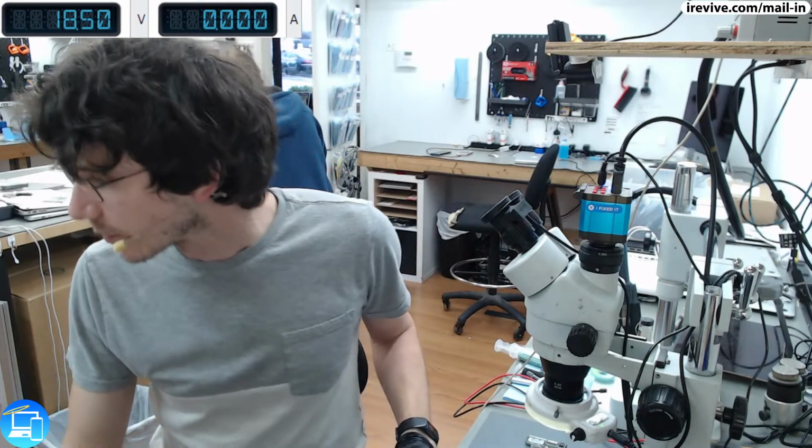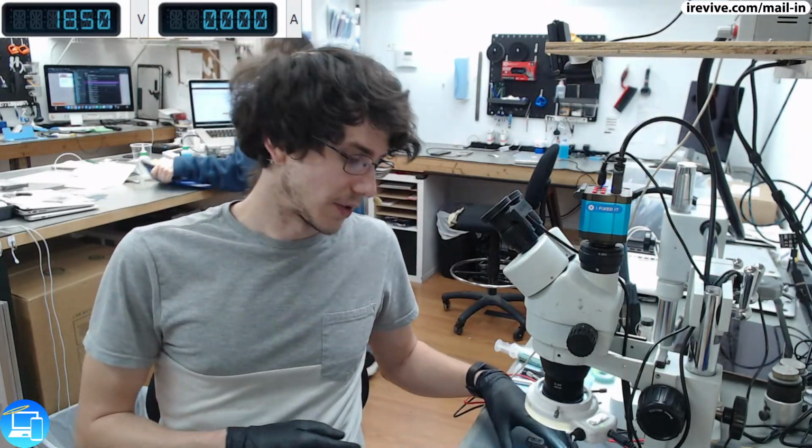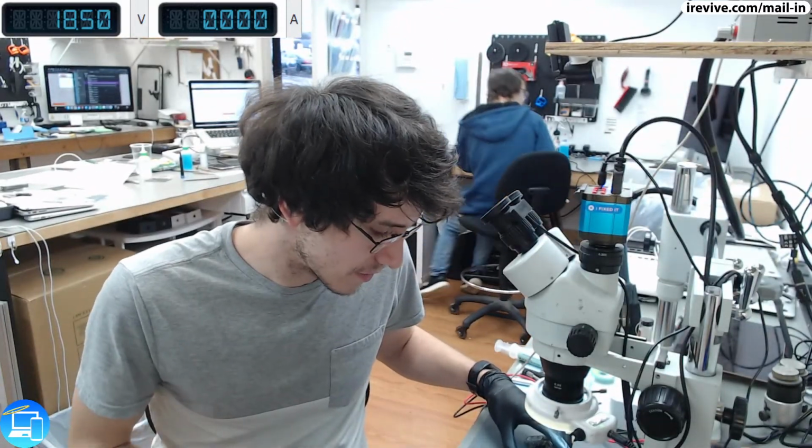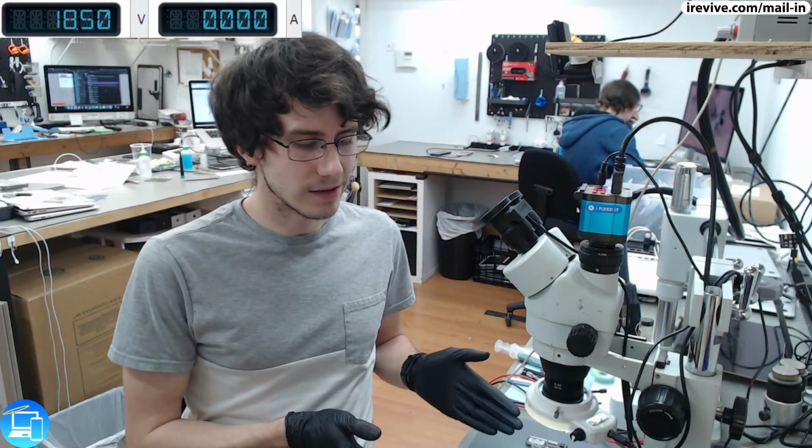So today we have ourselves a MacBook Air. It's an A1466 model, manufactured between 2012 to 2017. Looking at the SPI connector on the logic board, and also going off the board number, which is an 820-00165, this tells me this is either going to be a 2015 model or a 2017 model. We can confirm by checking the serial number, but all I need to know is that this is a